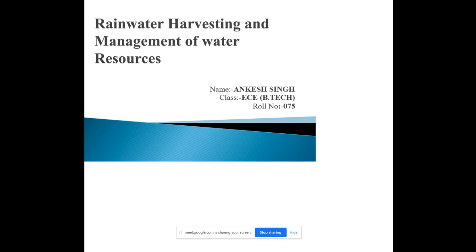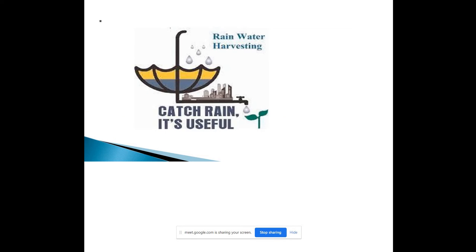Good evening, ma'am, and good evening, my friends. Today I am presenting my view on rainwater harvesting and management of water resources. Rainwater harvesting is the collection and storage of rainwater that runs off from rooftops, parks, roads and open grounds. This runoff water can either be stored or recharged into the groundwater. A rainwater harvesting system has the following components. It has a catchment from where the water is captured, and conveying tools, that is the drainage pipe, which carries the water from